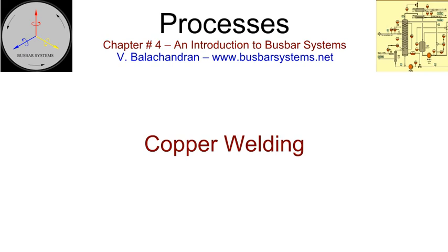TIG welding is generally limited to thin sections, while MIG welding is carried out on thicker sections. Because of the high melting point and very high thermal conductivity, to obtain a satisfactory weld, it may be necessary to preheat the conductor before welding. The preheating temperature will depend upon the thickness of the conductor. It is recommended to preheat the conductor of thickness over 3 mm.